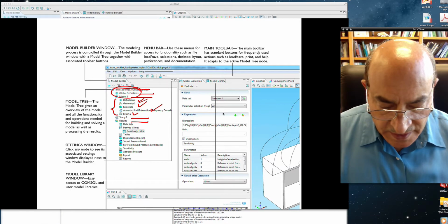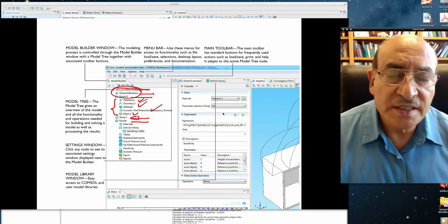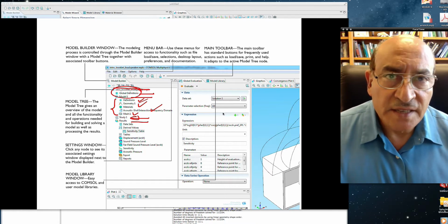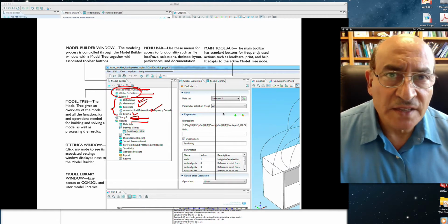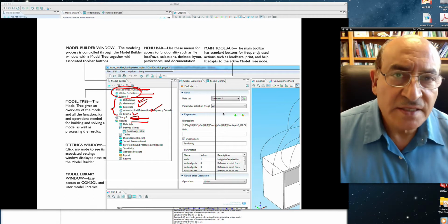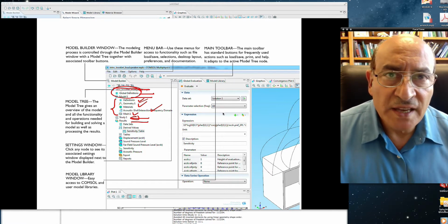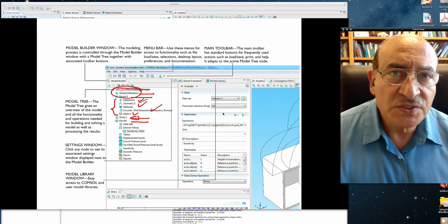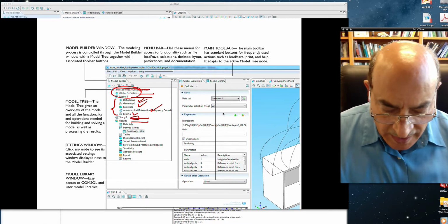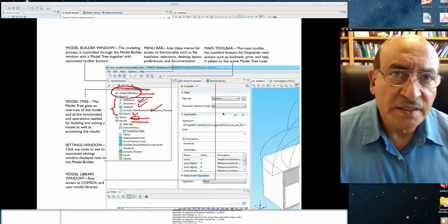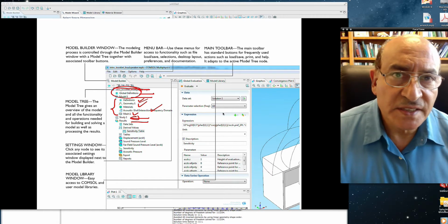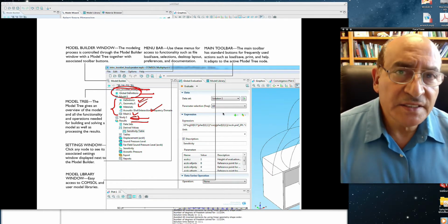Then the next node is the study node, and in the study node we will select either a time-dependent or a stationary, which is static, a steady state, or other forms such as frequency domain analysis, or other analyses. But here in the next example that I'll show you is going to be a stationary problem. There is no dynamics, there's no time dependence in it. And then after we determine the study and decide on the parameters that describe the study, then we will get the results and then display the results.